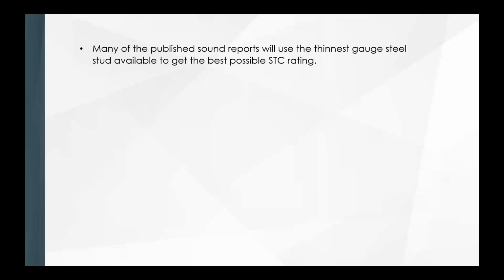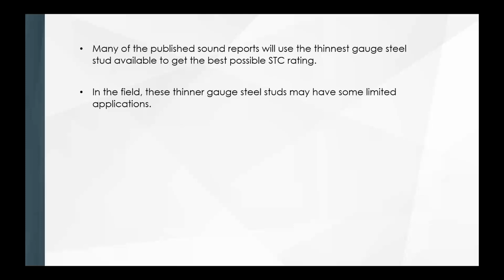All right, another kind of dirty little secret here. So many of the published sound reports will use the thinnest gauge steel available so they can get the best possible STC rating. Let's face it, if you're selling studs and drywall, you want to publish the best possible STC rating. And how do you do that? You do it with the thinnest gauge stud. But in the field, especially when you get down into 15 mil studs, the thinner gauge studs may have limited application, limited heights, and might not be able to provide the limiting height requirement for your projects.